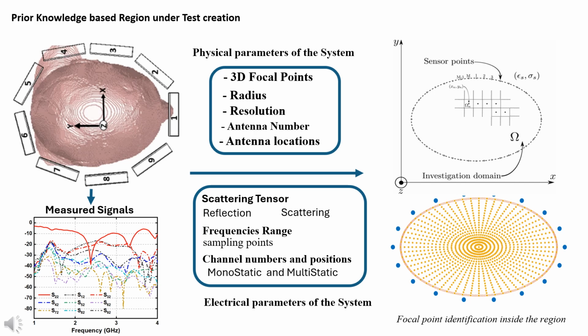Before the confocal algorithm is applied, it is crucial to determine the effective permittivity of the region being scanned. Permittivity describes how an electromagnetic field interacts with the material, and selecting the correct value is vital for accurate image reconstruction. By optimizing the permittivity, the system can more precisely map the interaction between the microwaves and the tissues, leading